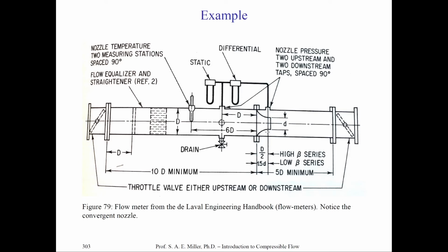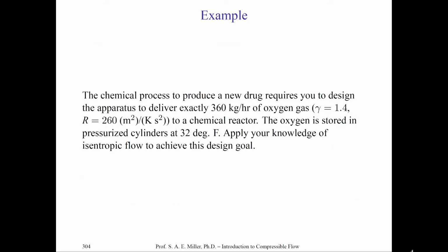This nozzle is designed to choke the flow through some choked area dependent on little d. The inlet flow is capital D. These butterfly valves, of course, open and close the flow. This is a type of flow meter where you can directly control the mass flow rate because, of course, the flow chokes at d. As we see, the mass flow rate is only dependent in this particular flow by that choked condition. Try it for yourselves in the following problem.